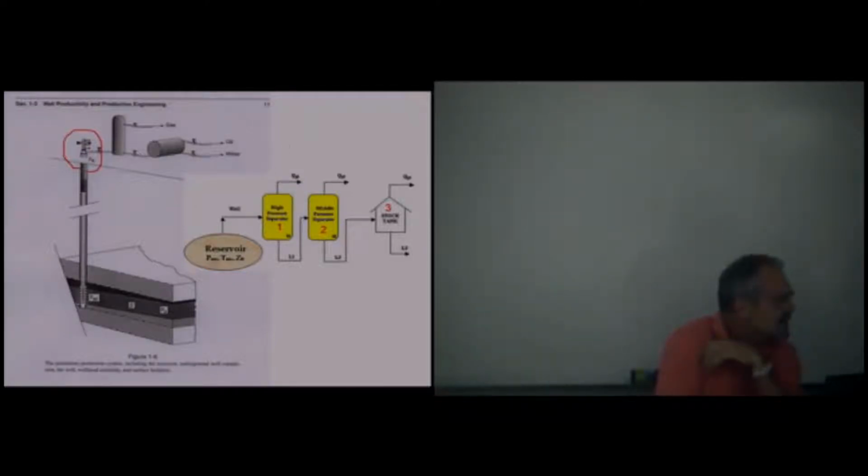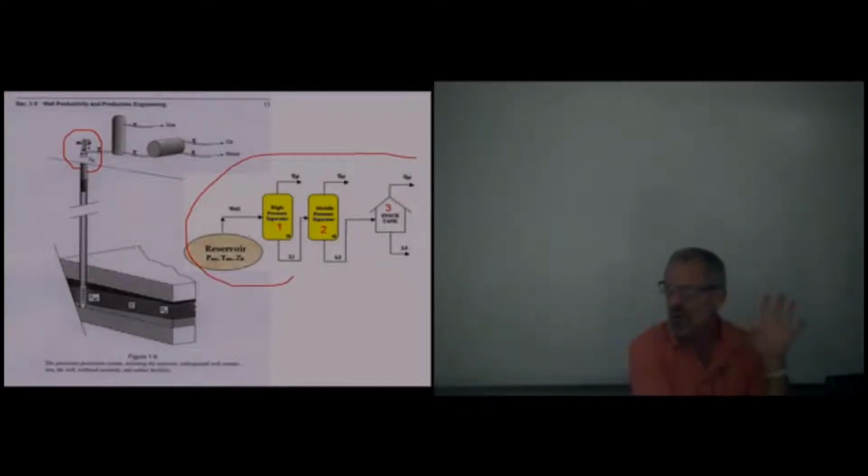Now I added this portion to our slides from last week. What we have here is the old school two-stage separation, and really we would call it three-stage separation because we'd have a stock tank out here, and although we only send it oil, it's got a vent cap at the top because otherwise on a hot summer day you'd build up so much pressure it'd blow up.